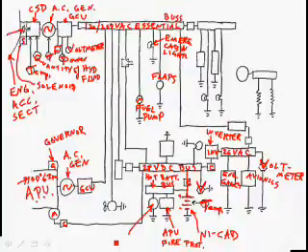And here, the inertial reference units. I know AS358 Advanced Avionics is not a prerequisite for this course, but the inertial reference units, you can only start them up on the ground. They need to be not moving. They need to be stationary when you fire them up so they can align themselves and be nice and accurate. You cannot realign them in civilian airplanes. You cannot realign them in flight. So you don't want to accidentally turn them off.